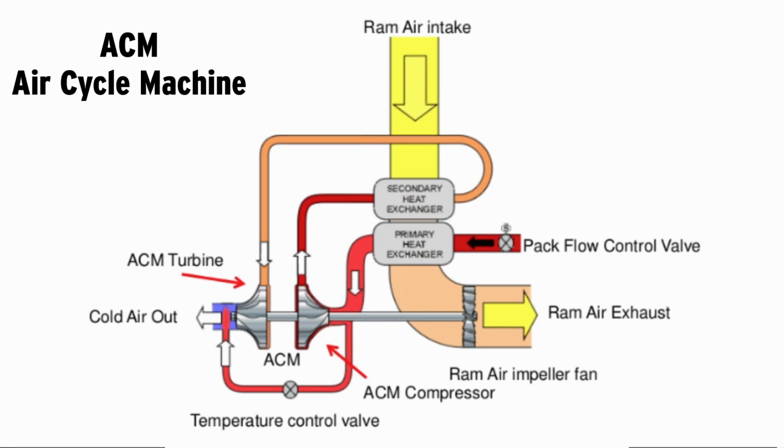That energy, that air that we super compressed and took a lot of heat out of already, is now going to be shot into this turbine that runs the compressor of that pack. And what that's going to do is that air is going to do a ton of work, and it's going to come out of there very cold. It can easily be below freezing cold.